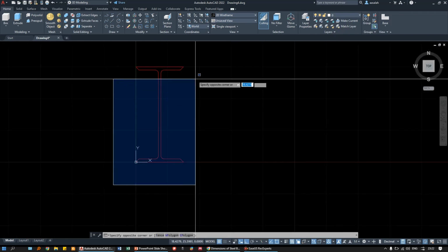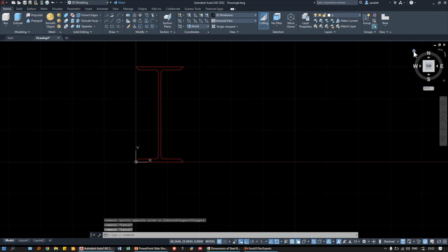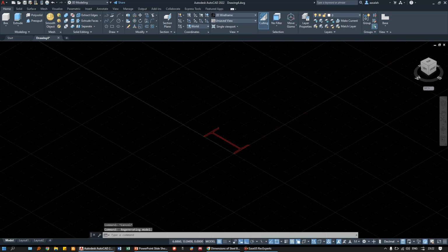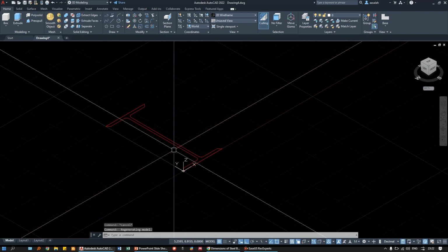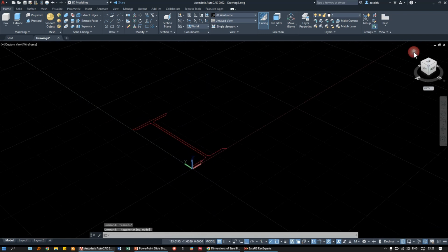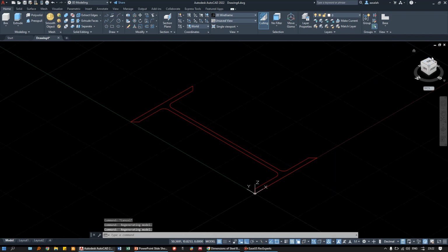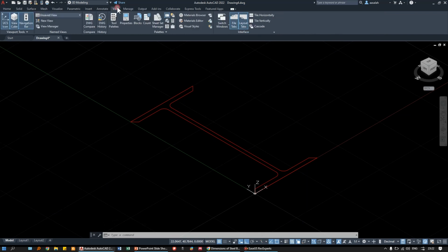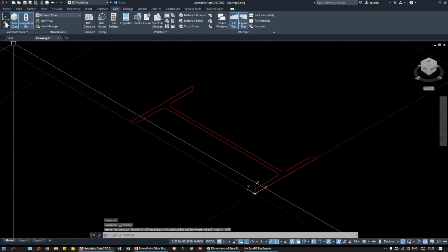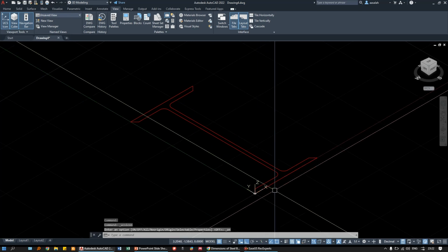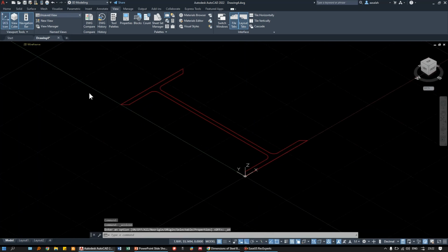After I establish the 2D section, I'm gonna switch into the home view, which is this one. I'm not gonna work on the top anymore. No, I wanna select the home. As we can see, the isometric view, when I select the home view, you can select from this cube, which is the view cube. If you are missing this cube, you can just simply go to view and then view cube. It will come back to you. As we can see, it can disappear and then it can come back. And here also you can see the coordinate system directions, XYZ.